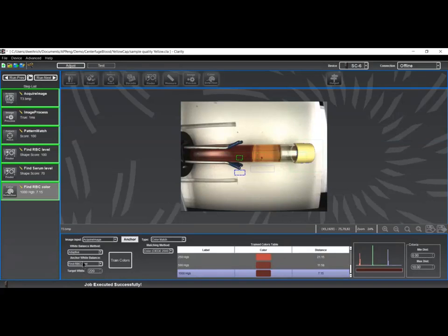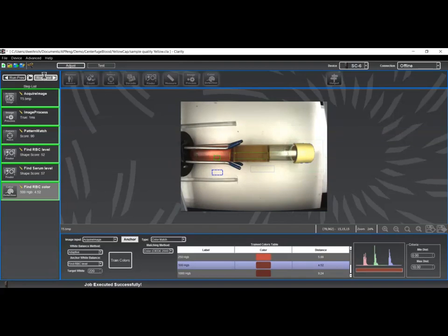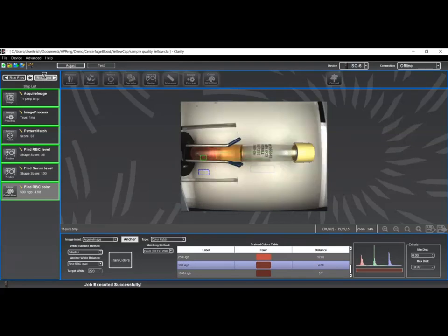The blue box that's moving along with my color sample area is the region of interest applied for my white balancing processing that adjusts the sample color to compensate for the illumination intensity or shading variation that happens across the different areas where my sample area is being taken.